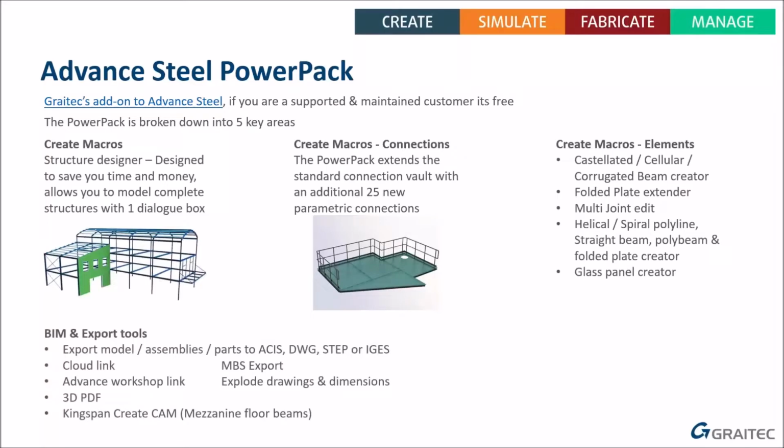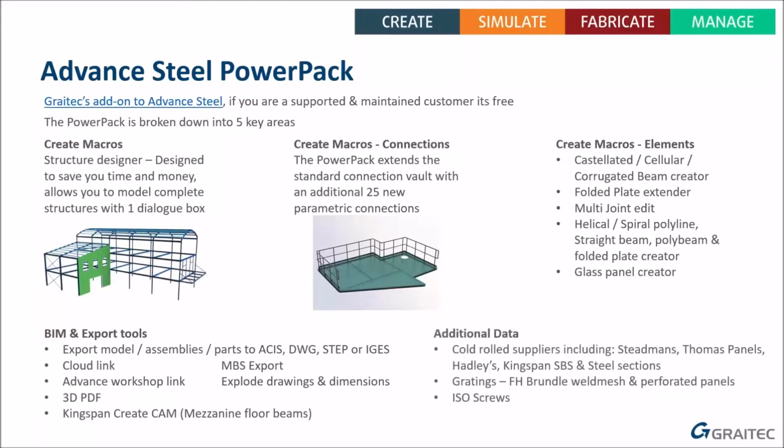We then have our BIM import and export tools. So if you need to export your model or individual parts to STEP or IGES for laser cutting, or you need to send to someone using Inventor, you can do that with one button. We can explode the drawings and dimensions. We've got some Kingspan CAM tools just for their mezzanine floor beams currently.